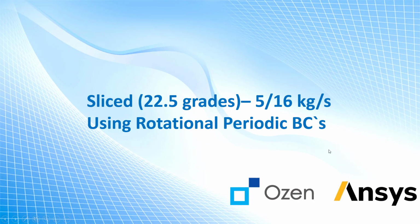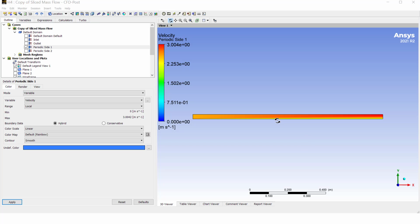Now let's analyze an additional case. We are going to use the same slice geometry with the same slice mass flow rate boundary condition, but now we are not going to use symmetric boundary conditions, but rotational periodic boundary conditions. Let's look at how this looks. Here we have the results for this case, and you can see that the maximum velocity is 3 meters per second. That is pretty near to the results that we got for the full geometry.